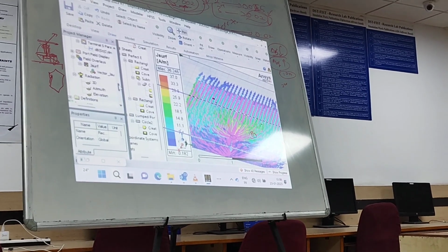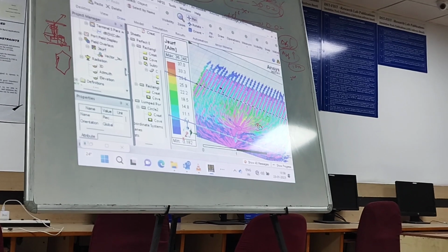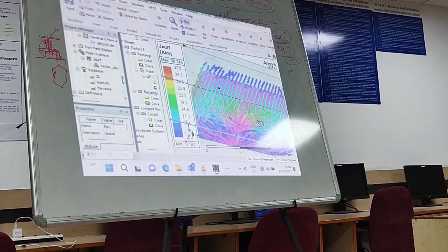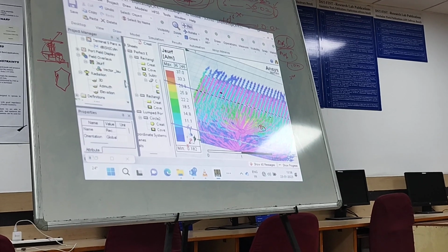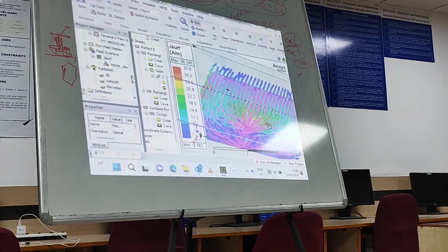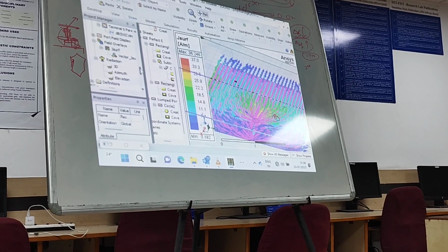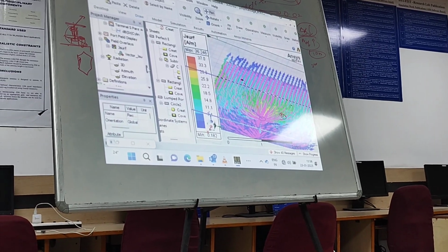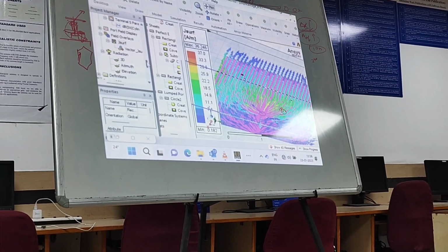Okay, that was about reflection coefficient. If the reflection coefficient is not neglected, like if it is not matched or the impedance is mismatching, because of reflection, whatever the signal I had sent as an electrical signal, nothing is going to be transmitted to the other end. So the first criterion was whether the signal I am sending is reaching my radiator properly or not. That was the thing which we were seeing there.